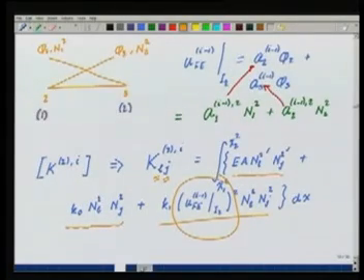Now this again we do using numerical integration. So what will we do? Let's say I have the element and here I have some Gauss points in the master element. So again we will go to the master element. These psi_m are your integration points in the element. So K_lj for element 2 will become the integral from -1 to 1 by our standard mapping.